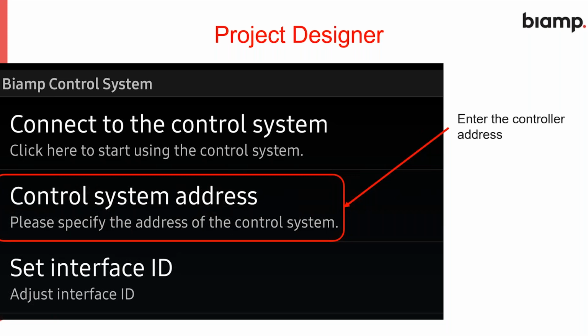So once you get there, the main display at the top, this is the main adjustments you have to make. The first thing you have to do is use the touch panel to set the control system address. This is the address that we discovered earlier on. In our case, I think it was 192.168.0.178, something like that. So we go into this menu, set the IP address of the control system. This is telling the touch panel where to find its user interface to display and interact with.